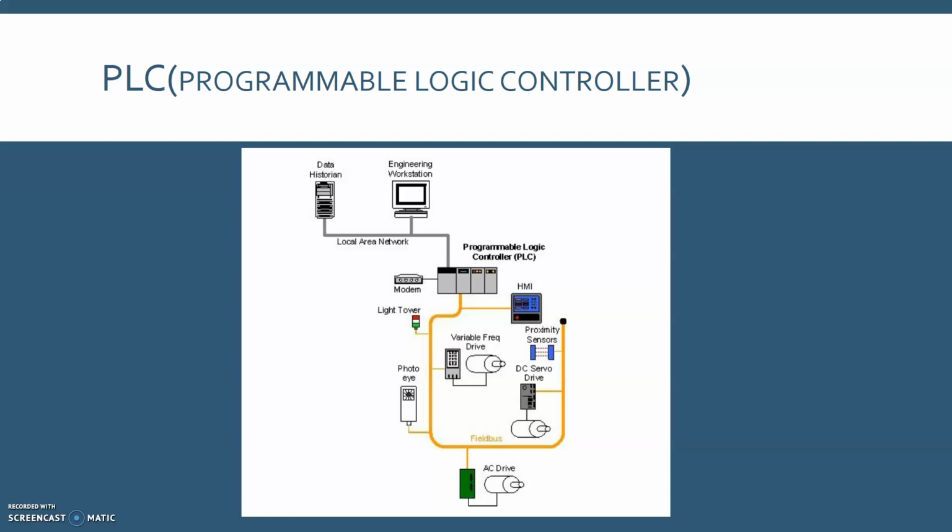In addition to PLCs used in SCADA and DCS, PLCs are also implemented as a primary controller in a smaller control system configuration to provide operational control of discrete processes such as automobile assembly lines, power plant soot blower control. These topologies differ from SCADA and DCS in that they generally lack a central control server and HMIs, and therefore primarily provide closed loop control without direct human involvement.